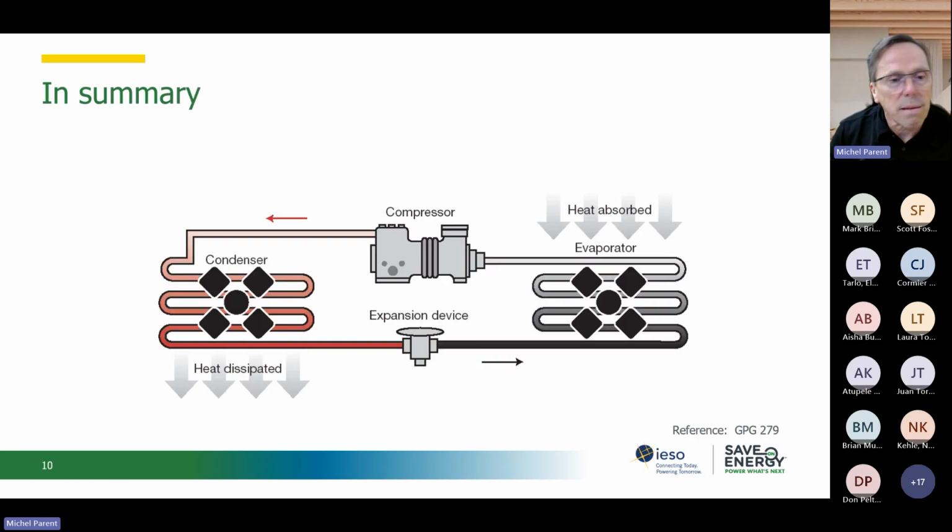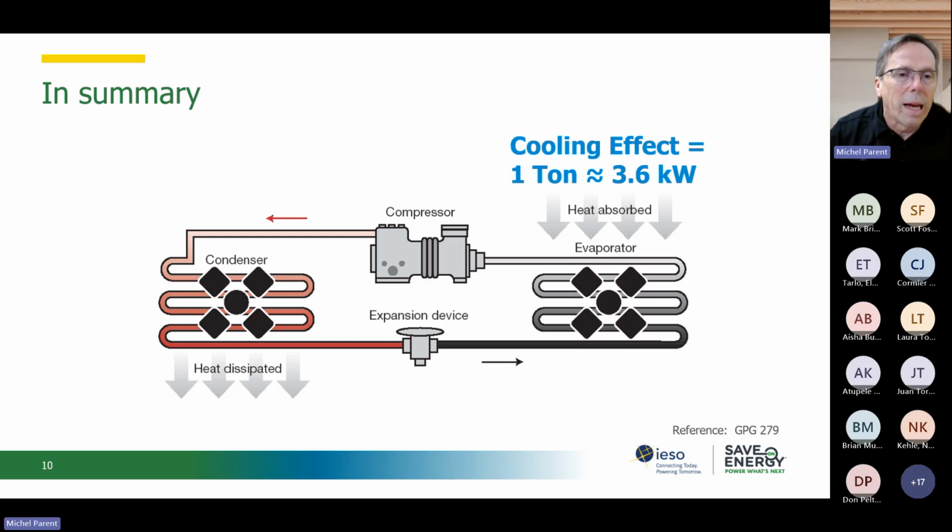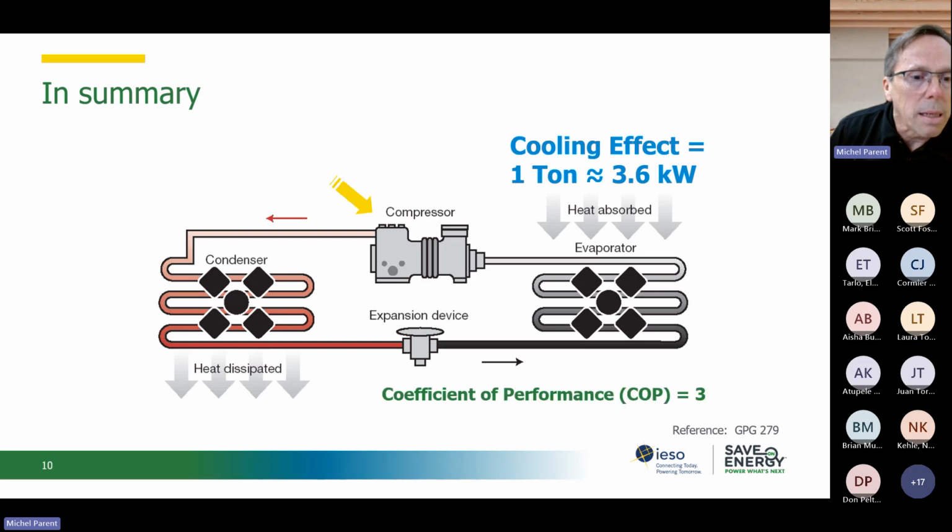So that's the same principle for anything that's refrigeration driven, that's compressor driven, using the vapor compression cycle. So the reason we say that a heat pump has an efficiency greater than 1 is because it will capture some heat from the source right here from, let's say, outside air. It's going to absorb, let's say, 1 ton of heat. The compressor will provide some energy to compress it, so that will add to that energy, and it will release all of that heat into the building.